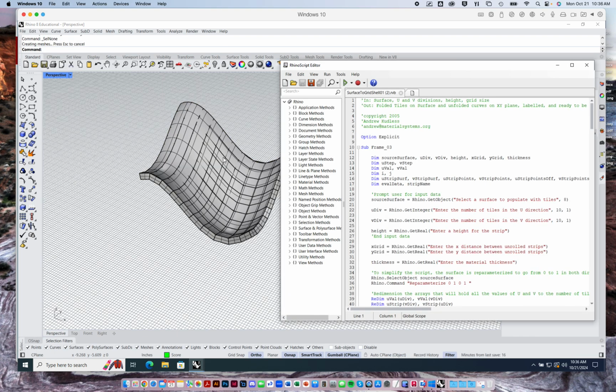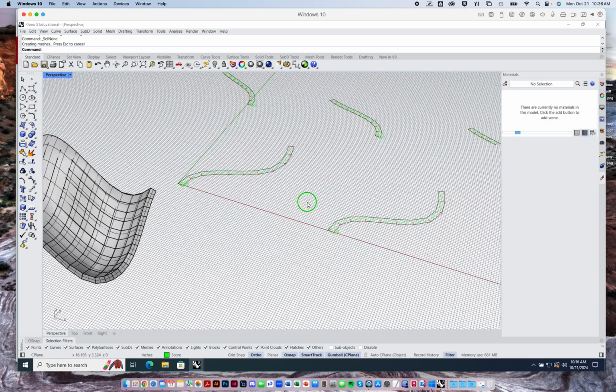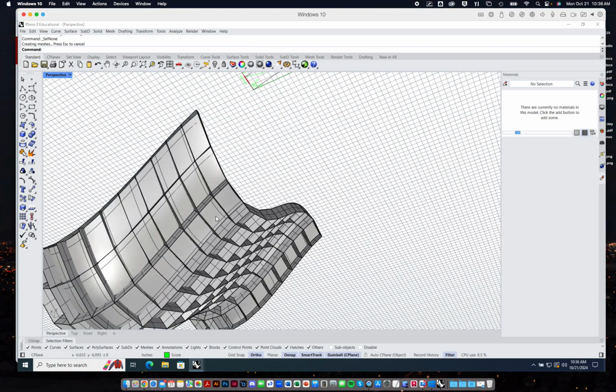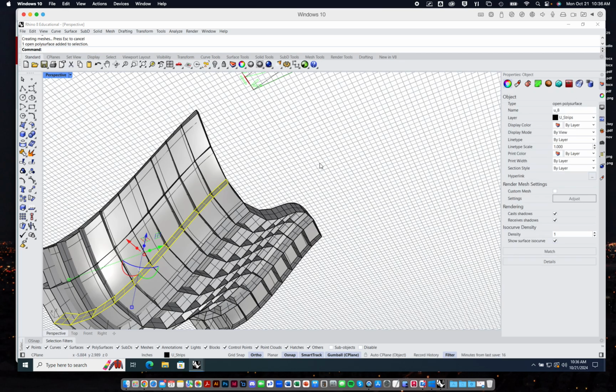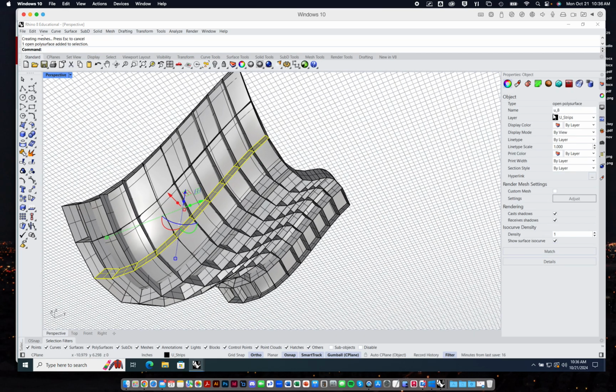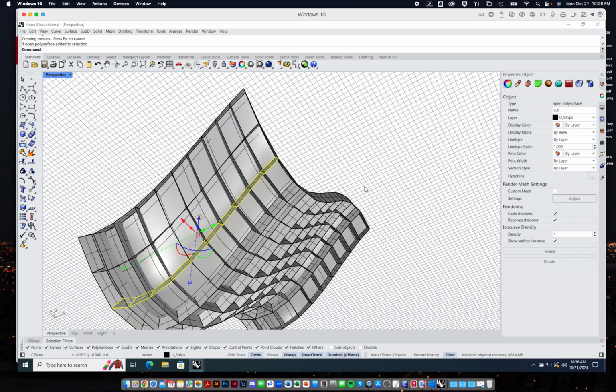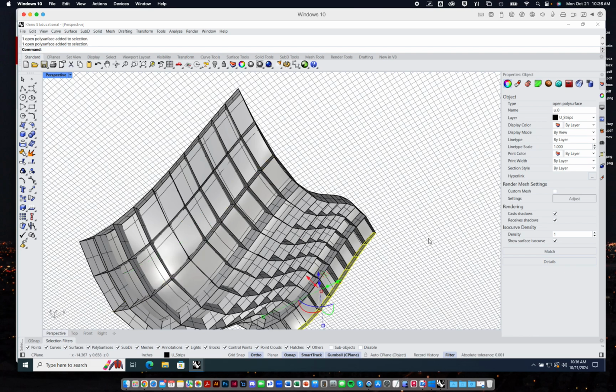And now it's just doing a bunch of stuff for me. And it's done already. That's very quick. Let's just take a look at what it did. First of all, three-dimensionally, I populated the model with these strips. And if I go to the Properties tab, you'll see that each strip has also a name, right? So in the U direction, let's say the equator, so latitude, I have U0 all the way to U10, right? 10 divisions, 11 strips, starting from 0 to 10.